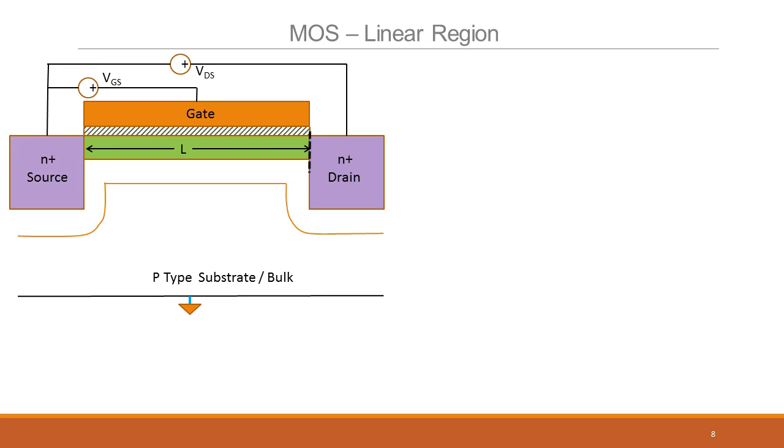When you do this, if you look at the junction here, this is where the electrons will now flow out. So we'll just use this as a point of observation. Current is nothing but rate of flow of charge, as we have seen. For low VDS, velocity, as we have seen before, is proportional to the electric field applied. So it's mu times E. And what is the electric field? VDS is applied across a distance L, so it's mu times VDS by L. And this holds good for low VDS.